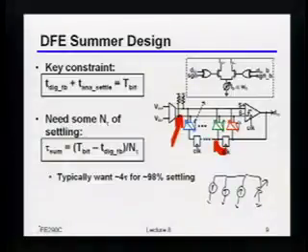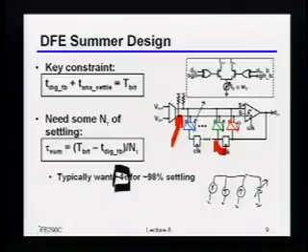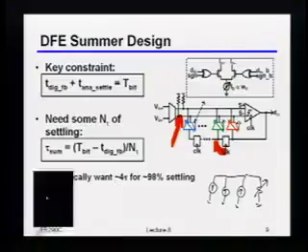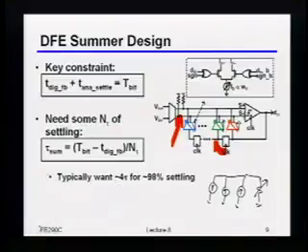Well, this bandwidth is just set by this resistance, right? So basically, the bandwidth on this node is exactly this number that I'm quoting here. So, you are right, by the way, that there may indeed be another preamp inside of the comparator, which would then mean that that also has an implication on how fast this can settle. But the good news is that it's also fairly straightforward to figure out what the impact is. You can include that as a digital delay if you like. Okay. Does that make sense?